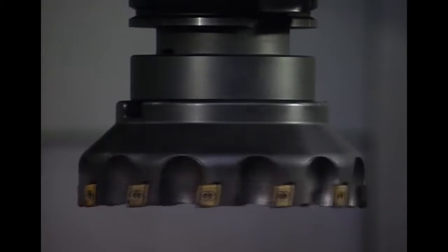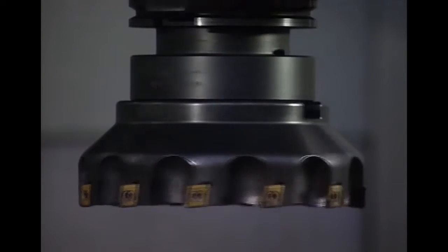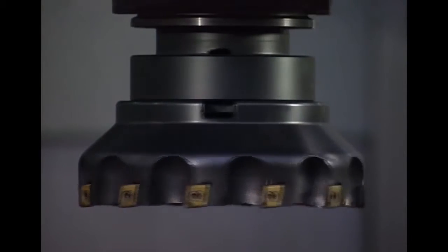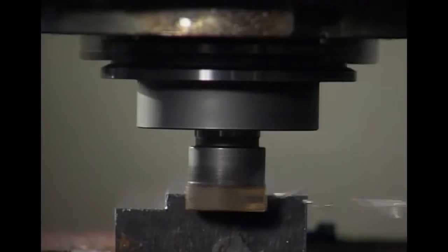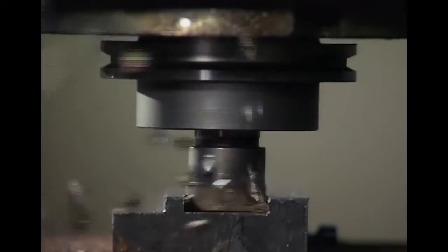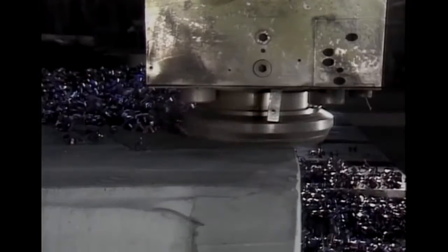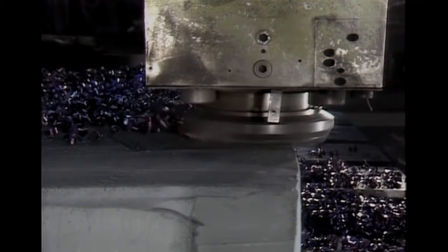Face milling cutters effectively generate flat surfaces with the spindle perpendicular to the work surface. The cutter body has multiple pockets to accept a variety of indexable insert types. As the cutter rotates, each insert edge alternatively enters and leaves the cut, removing a small amount of material in a short, discontinuous chip. The chip thickness at the start of the cut is called the undeformed chip thickness.